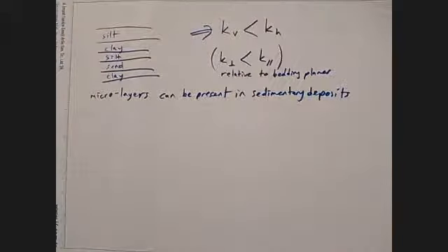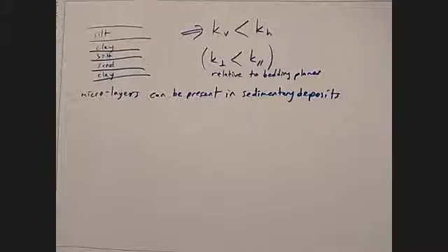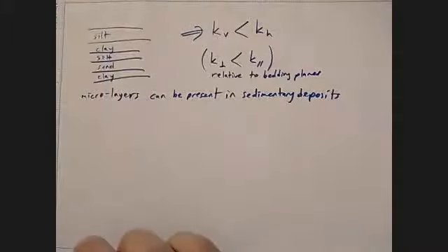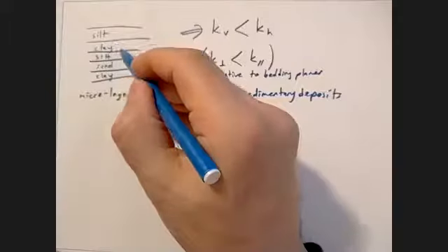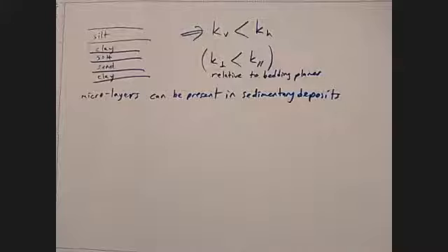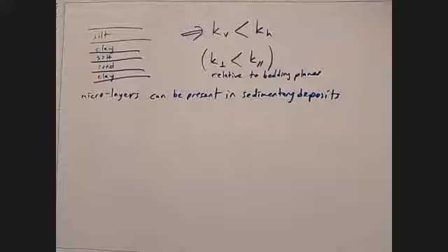Now here is the problem. When you go and take a sample out of soil, most of the time what you end up doing is getting a subsample from a random layer and in the vertical direction. So most of the time you are underestimating the hydraulic conductivity.